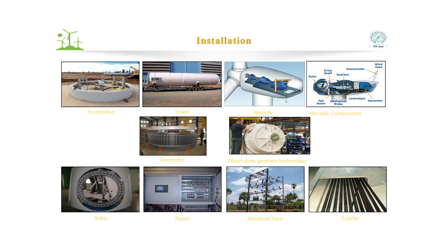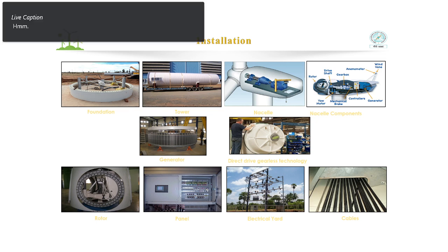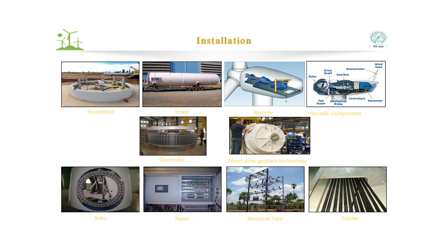because concrete is weak in tension but very strong in compression. What they do is they pre-compress the concrete so that it never goes into tensile stress during alternating stress reversals like tension and compression. That way the concrete tower will be rugged. You can change the machine without changing the tower.